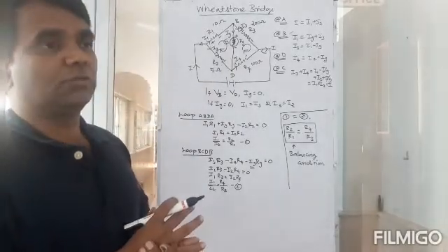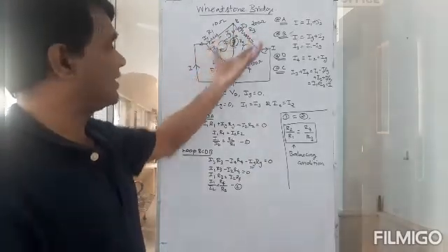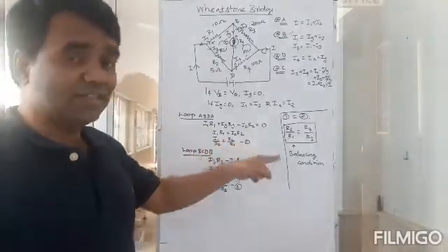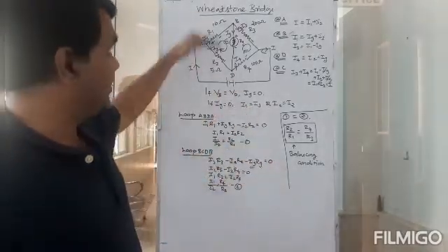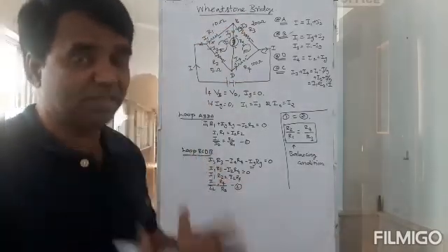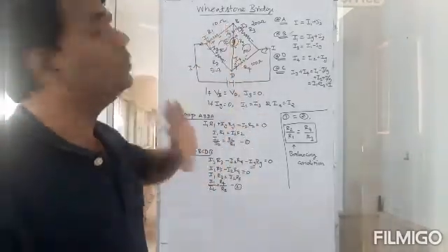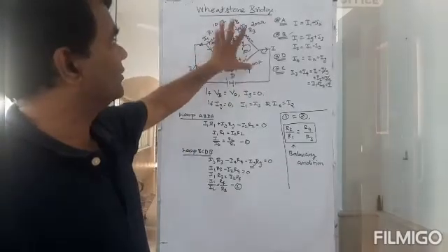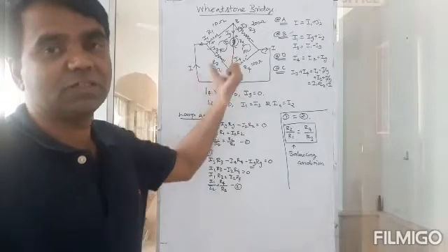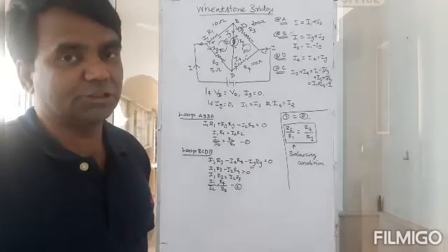So, if you have different resistances in this bridge, again all the currents will be available. Even Ig will not be equal to 0. But in this balancing condition, when R1 by R2 is equal to R3 by R4 is met, then Ig will be equal to 0. No current will flow through Ig. So you can just take it away. It's as good as not connecting any galvanometer there. It's as if it were not present in the circuit. That is what we call a balancing condition.